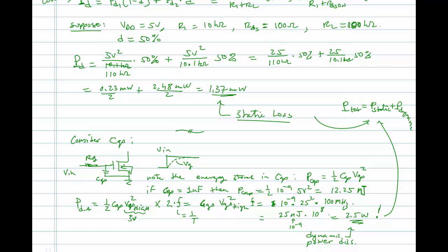And so that's the battle that's always being fought, to try to make things go faster you want to shrink them in size. You can reduce the energy stored in the parasitic capacitance, one, by either reducing that parasitic capacitance by designing smaller transistors, smaller feature sizes, or two, you can reduce the operating voltage, right? So instead of charging it to 5 volts, you can charge it to 3 volts maybe, if that's still enough to turn on the transistor.